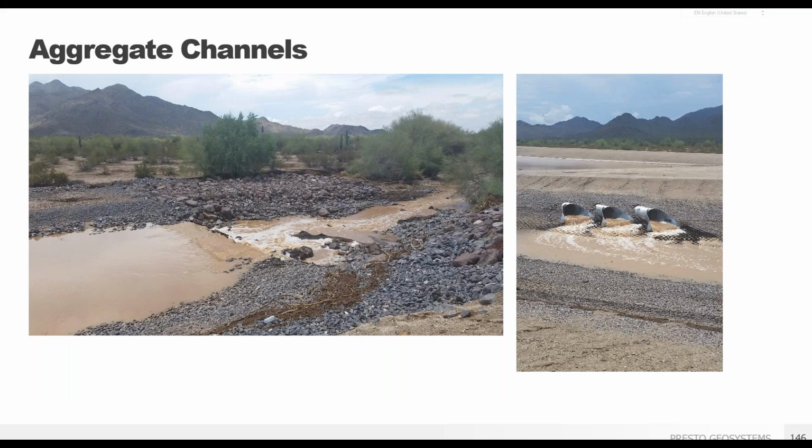And here's the installation under typical flow conditions. You see the technique tip of adding drop structures, and several were designed throughout the channel to reduce velocity before reaching the end of the channel, so the water will be transported to the groundwater system. With the aggregate protection system, there is little to no maintenance required, since the aggregate is confined and won't need to be replaced, and the channel is large enough to accommodate large storm events without overtopping.